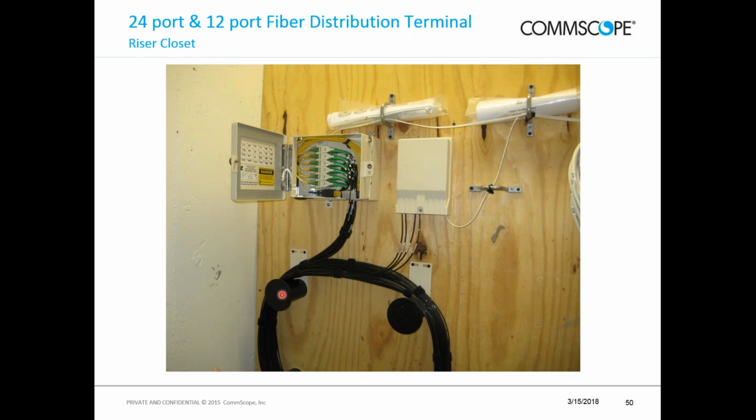Remember what I was talking about pre-terminated cables? You need to manage the slack. So this is how this contractor decided to manage the slack, which I think is good. But, again, this is where the advantage of a field terminated connector comes into play, where you can cut the connector and cut the cable to length, and you don't have to manage this over-length slack. They did a nice, clean job of it. It's just that it's additional work.